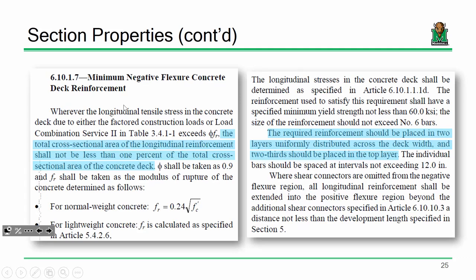All right, and then for the purposes of our calculation, when we're trying to do spacing, we can just assume that they're number 6 bars, which, let's see if y'all remember. What's the diameter of a number 6? Let's see if we remember. So who said that? There, 3/4, right? Number 6 is 6/8 or 3/4. Whoever said that.